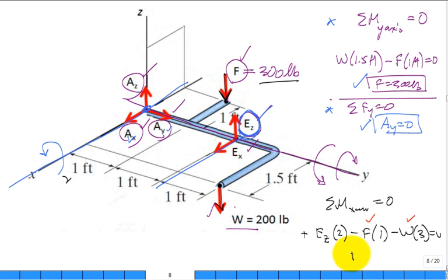Okay. Now, some people, when they're first starting out, will put that it's 450 foot-pound force. No, it's not foot-pound force. This is truly a force. It's not a moment. So please be careful when we're writing things out. Somebody says, you didn't put a unit on 0. That's the one case where it doesn't matter.